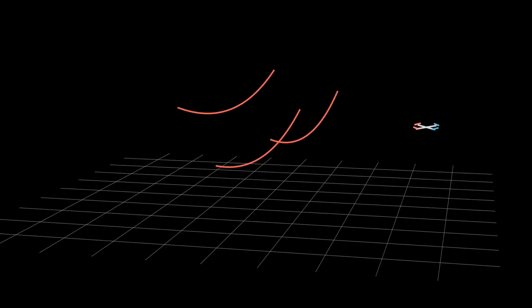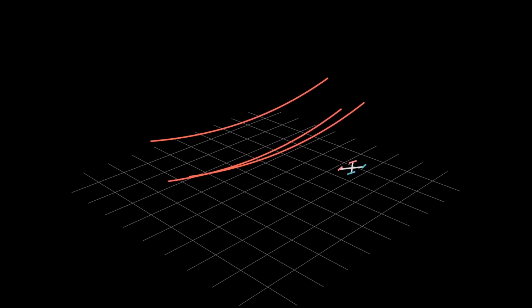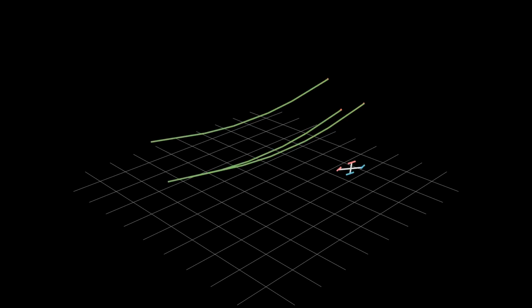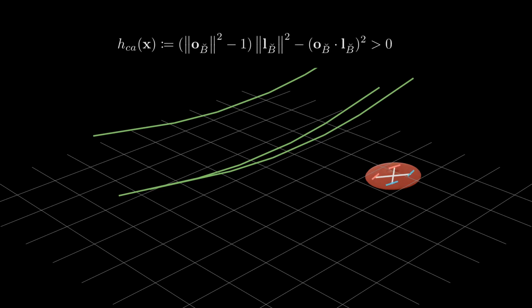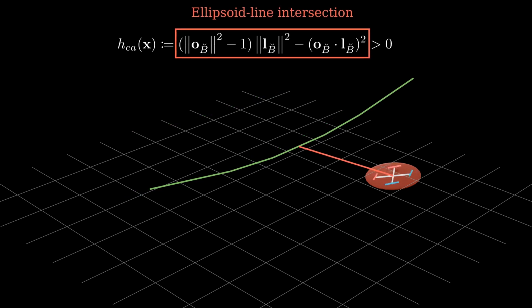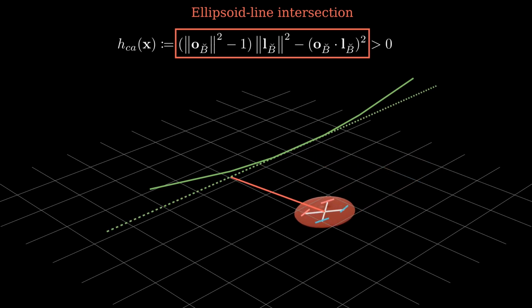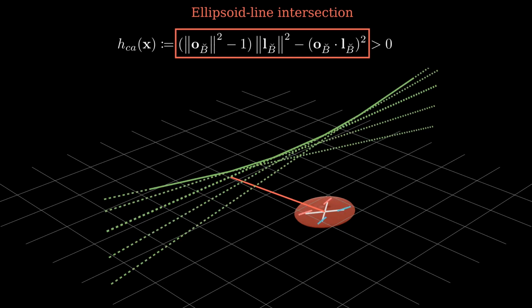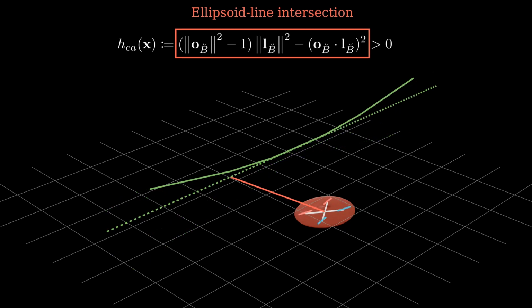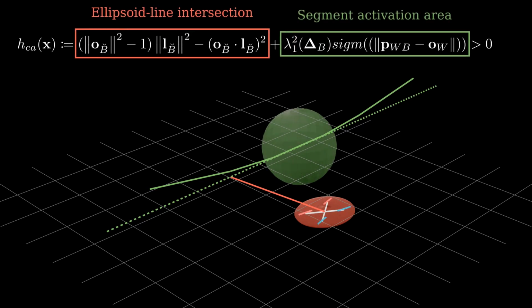To efficiently represent the perching problem, we model the power lines as sets of segments and the quadrotor as an ellipsoid volume. This way, the distance between a quadrotor and a segment can be modeled in a closed form. However, this formula works by assuming infinite length lines, which can end up restricting an important fraction of free space. To solve this, we add an additional term so the collision with the segment is only modeled in its surrounding area.